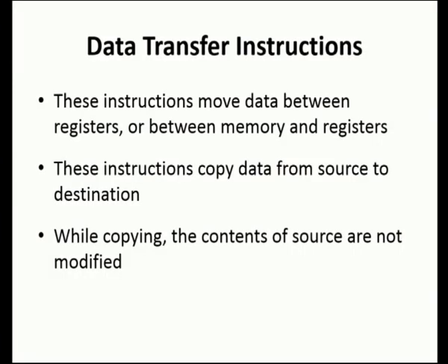To reset or to clear the registers, we can follow the machine control instructions. Now, we will discuss each instruction with the corresponding format. The mnemonic format is very important to write the program. So, first we will discuss data transfer instructions. This transfer instruction is used to transfer the data between the registers or between memory and register, or we can load the data from the source into the register, that is either we can store the data or we can load the data. For that we have two kinds of instructions, load and store.